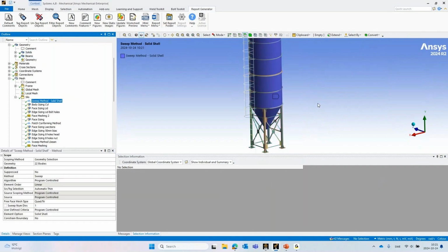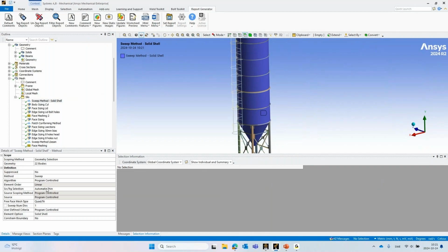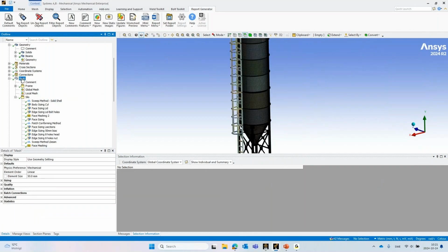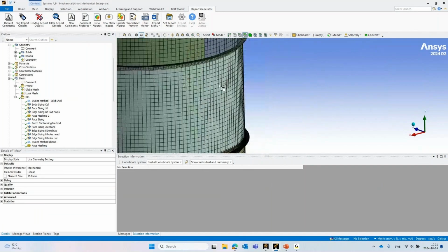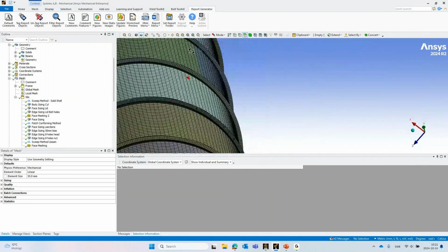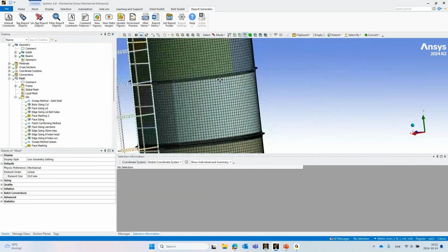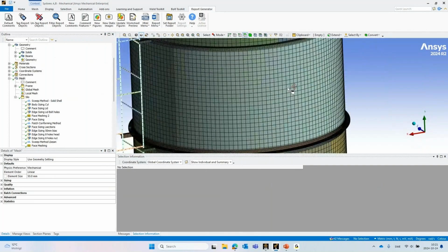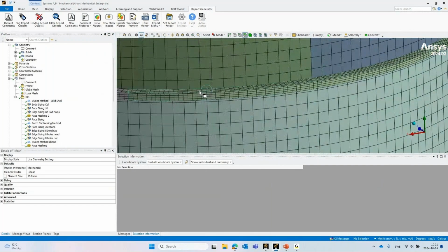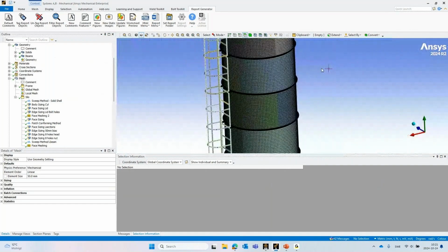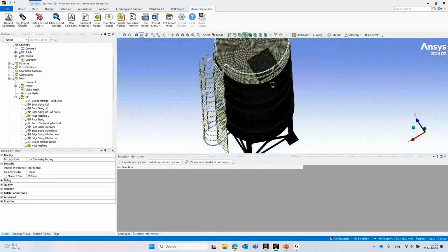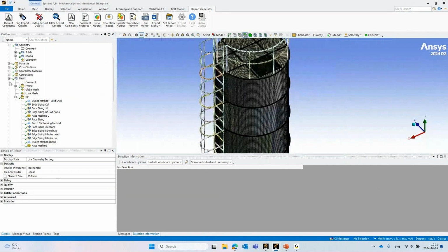So selecting these thin parts, defining them as automatic thin will give you a good mix of being able to have quite large elements and not having to care about the thickness of the plate because it's a shell formulation. Other parts like flanges, I use ordinary solid elements and just used sweep method. So setting this up, a number of, what else do we have here?